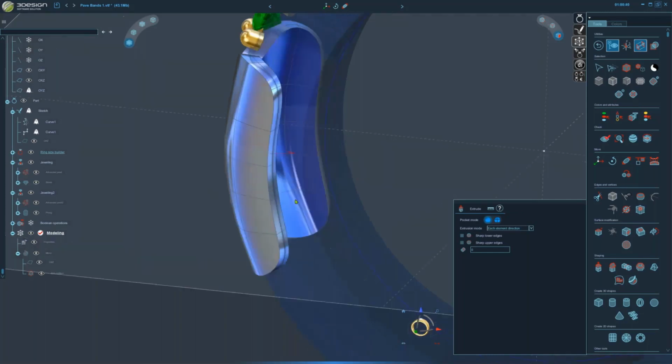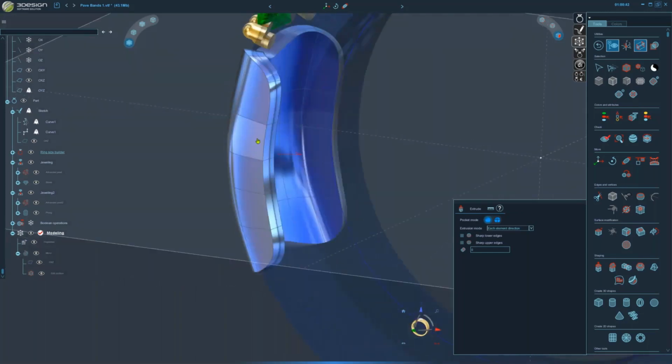So that's pretty much done. I want to soften maybe some edges here. When we do your shelling, it by default gives you hard edges. I'm happy with the hard edges on the inside, but I want to soften the inside here. Go in my edit tool. We're going to take a look at the edges.